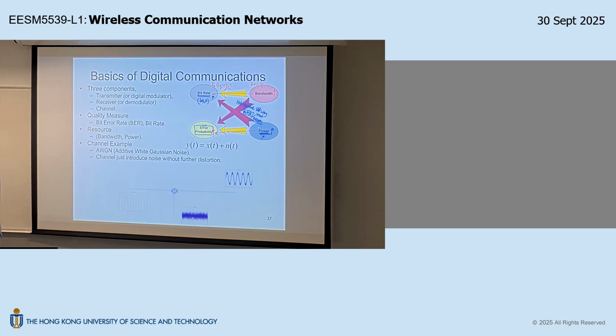So that's the reason you can, without calculation, immediately see this comparison. Okay? So if I draw the error probability versus signal-to-noise ratio, for example in dB, both designs will have this curve. But this one will be like 16 QAM, and this one will be like 16 PSK.